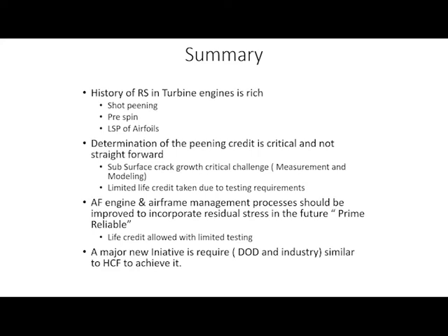Subsurface crack growth is a critical challenge, both from a measurement and modeling standpoint. And life credits can only be taken if you've done extensive, and I can't emphasize the word extensive enough, testing. Like I said, 4 to 5 years, at least 4 to 5 million. It's probably more like 10.